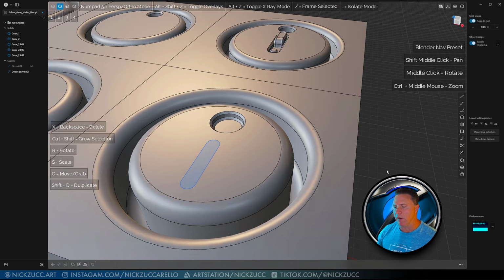And then I could say, I want to do a difference between this shape and this shape. So I select this one, and then I tap Q, and that's going to give me this right here, which is not what I want. I'm going to hit Escape for that. So as you can see, the selection order actually matters for what's the difference. So if this is my main body, and I select this, hold down Shift, add this one, then tap Q, this is going to give me the difference that I'm looking for. Okay, and if I hit OK, that will finish that off.